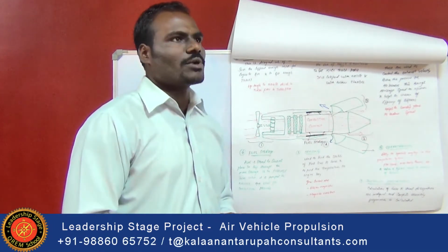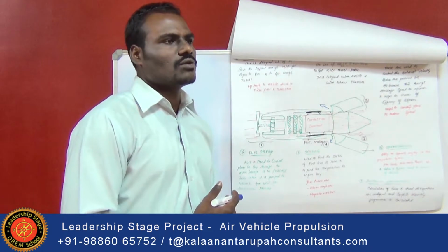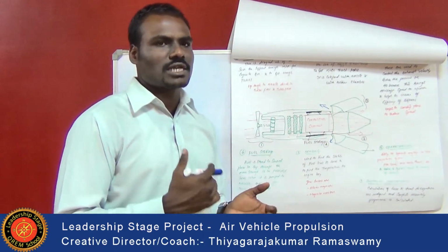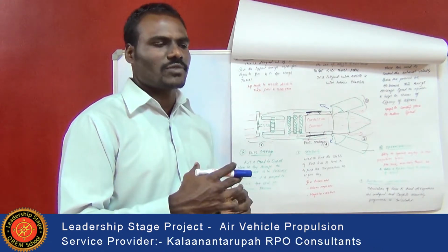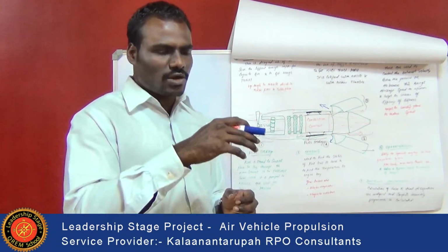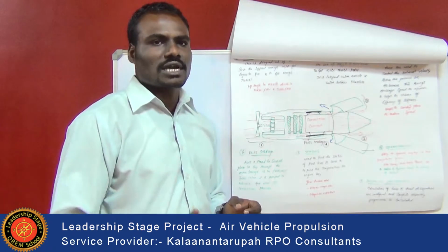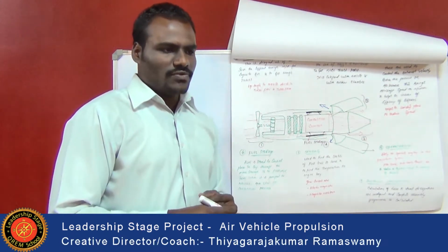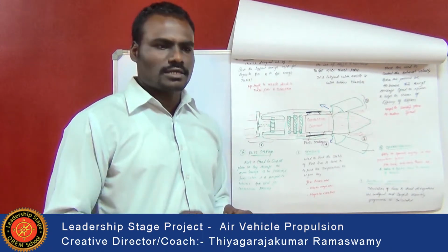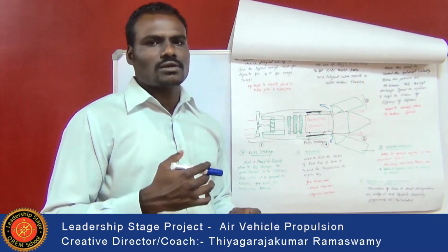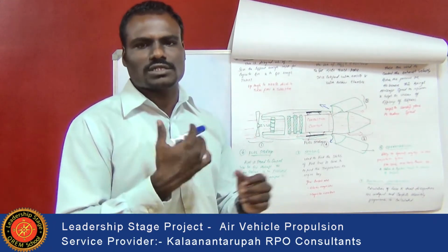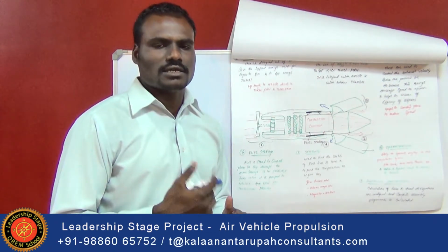One of the operability features we are going to see is the cowl structure. In a nacelle structure, there is a cowl at the engine which covers the engine part of the propulsion system. If some repair is needed at the engine part, we do not have to remove the entire nacelle structure to find the fault in the engine system.